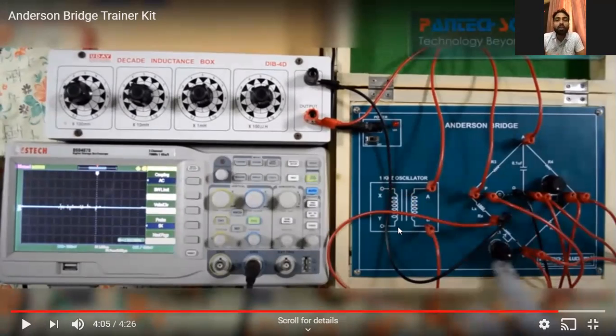So see how simple and easy it is. If suppose physically you have this slab in your hand, it hardly takes only 5 minutes to get all these values. Just connect it, adjust it, and find out the zero readings that we have already gone through. If you see here, no fluctuation. They are having a CRO. We can also connect the CRO. We can connect the headphone. We can connect the galvanometer. Whatever the requirement is, you can connect your own things. You can choose your own one. That's a very simple process. And by this, you get the unknown value.